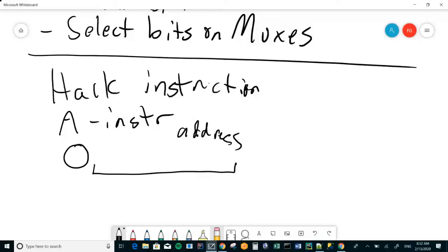Namely, you're going to be accessing this instruction bit 15 a lot when thinking about your load bits and your select bits, especially the load bits, right? If this is a 0, the load bit on the A register needs to be a 1. And the load bit on essentially everything else is going to have to be a 0. And by doing that, you prevent lots of inadvertent state updates from happening.